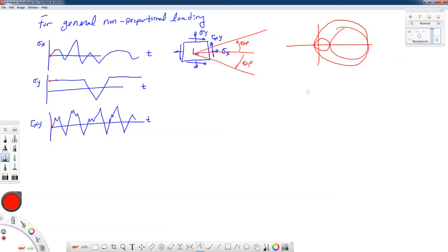So what we want is an approach that can accommodate tensile behavior in the plane of the material. It has to accommodate shear behavior in the plane, and it has to accommodate out of plane shear behavior as well. So if you know about the 3D Mohr circle, then you know about 45-degree out of plane maximum shearing stresses. So all these different planes in the material could be critical planes. They're potential critical planes.